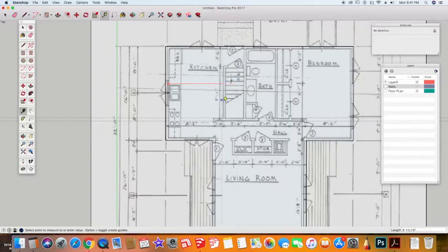And in this case, I'm going to eliminate this step here, and I'm probably going to put the second wall right here, and then I'm going to pull another guideline over 6 inches. And I am going to leave the bathroom approximately in that space, so I'm also going to add a wall here too, and I pull that over 6 inches. Type in 6 inches, and so here I can start to work the framework of what I want to do, and then I'm going to start to put these in.